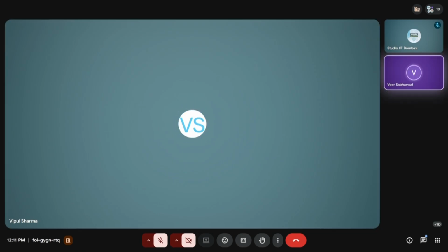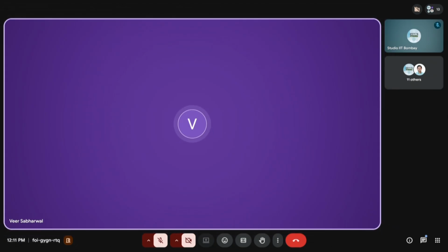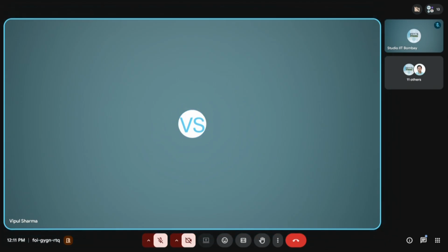Okay, sir. So I can use Magic and KLayout and those kinds of tools. Yeah, so KLayout you cannot use with the Sky 130 PDK because the PDK is not integrated with KLayout. But Magic you can use the way I showed you. For the schematic, you have to use Xschem and ngspice for simulation. They are integrated together, and layout with Magic and LVS with Netgen. These are the four tools which will be required.